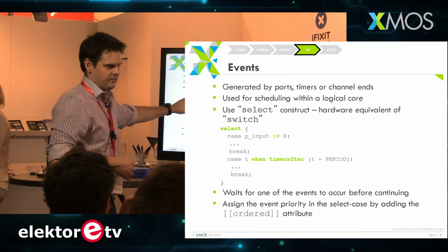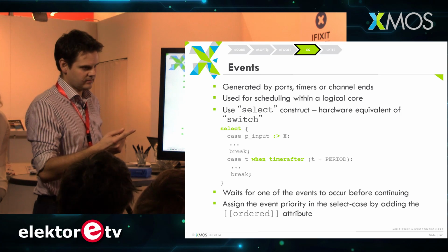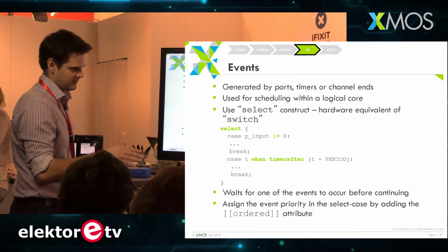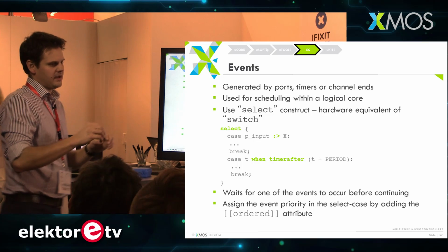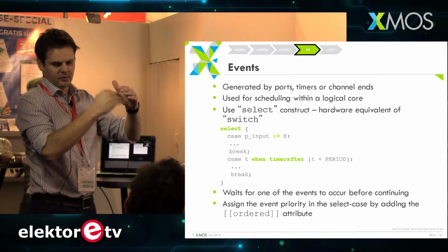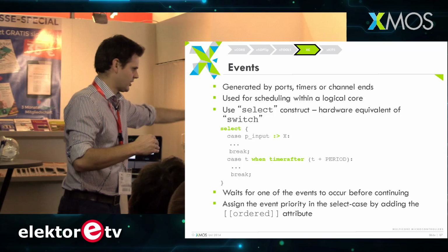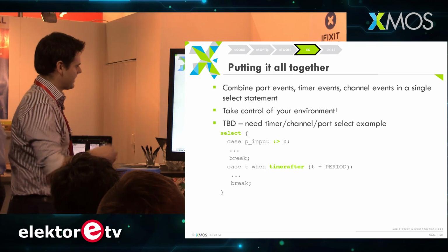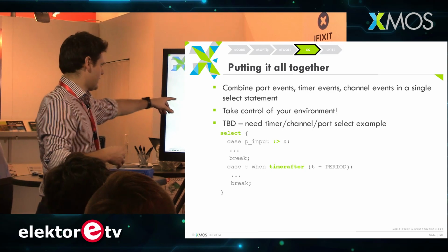All of the things inside the select statement will run on a single controller. So you need a single core, yes, absolutely. This will be inside a function, and that function will be declared in a par statement. You may have multiple functions in the par statement which will run concurrently, but within the function, this is a sequential operation.